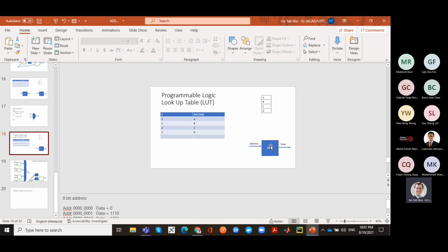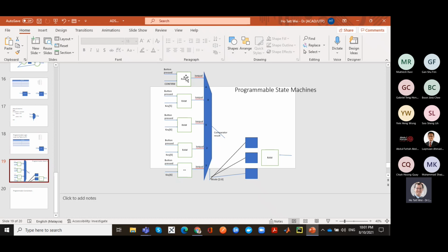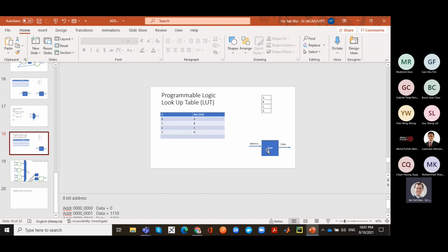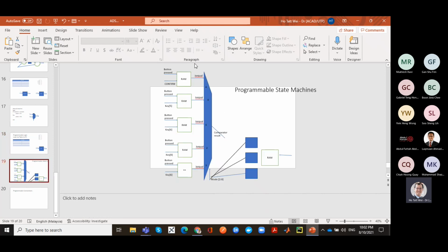Okay, so you see two places where this is implemented. In field programmable gate arrays, the actual computational task itself is implemented as a lookup table in memory. That's why your FPGA is full of static RAM. You don't really find that many logic gates in an FPGA. It's full of static RAM. Why? Because each static RAM, sometimes called a lookup table or LUT, is nothing else but a very small memory element, with just a few address bits and a few data bits out, and that can implement any of these computational blocks to do computation on the data path.